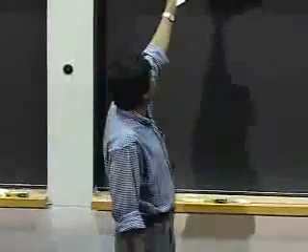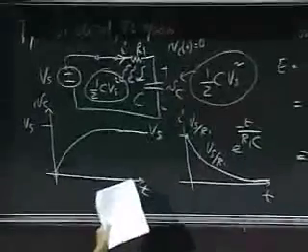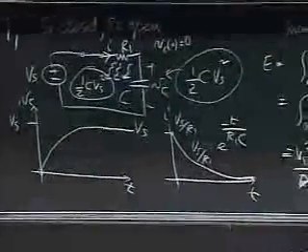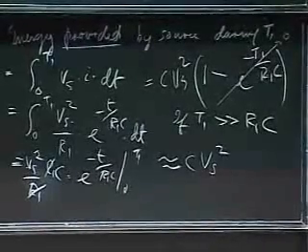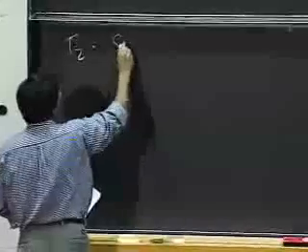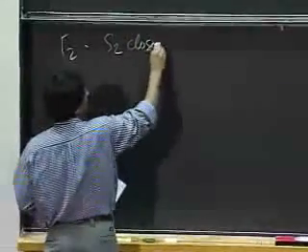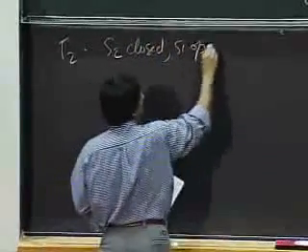And if you do a simple energy conservation arithmetic here, the energy dissipated in the resistor plus that stored in the capacitor equals the energy supplied by the source. Okay? All right, let's go to T2 now. At T2, S2 is closed and S1 is open.